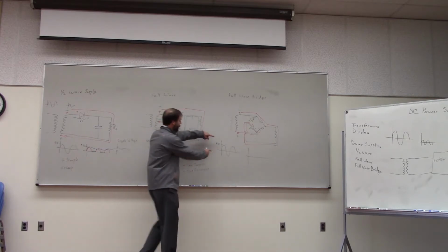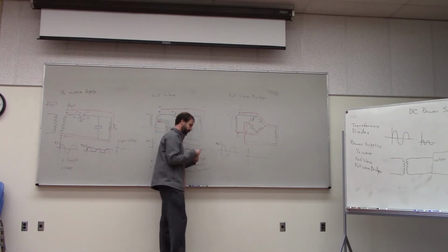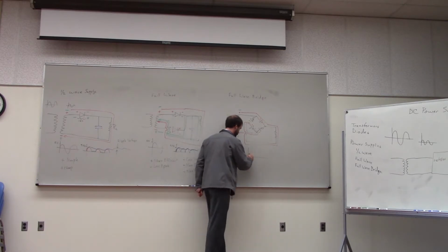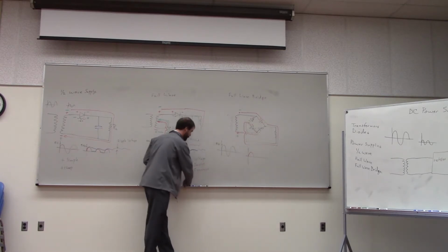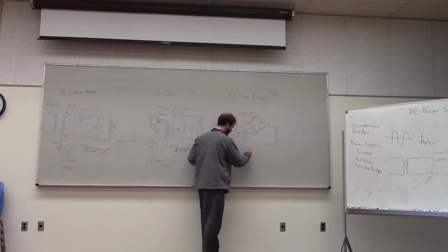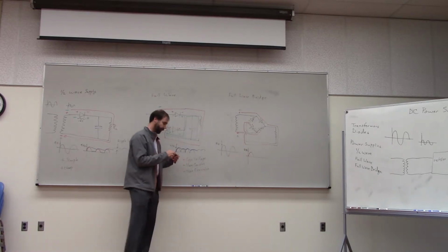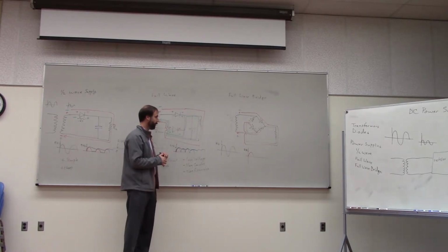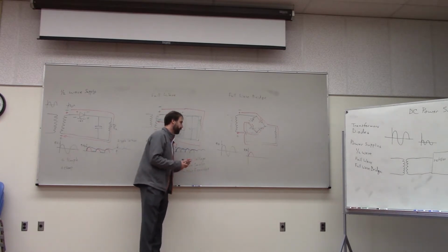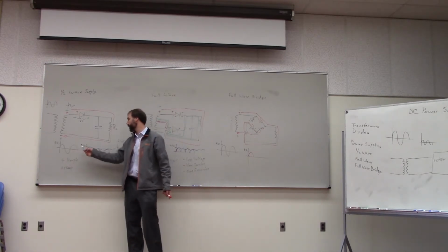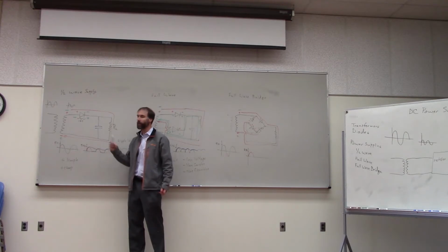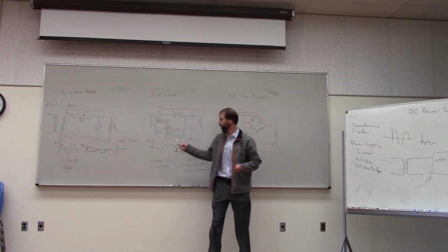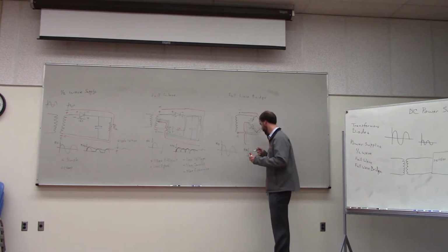But we're starting with the full 10 volts. So our output peak is 10 minus 1.2. That comes out to be 8.8. Exactly. So we get a peak output voltage of 8.8 volts. So not quite as much as the half-wave supply, but more than the full-wave supply, right?